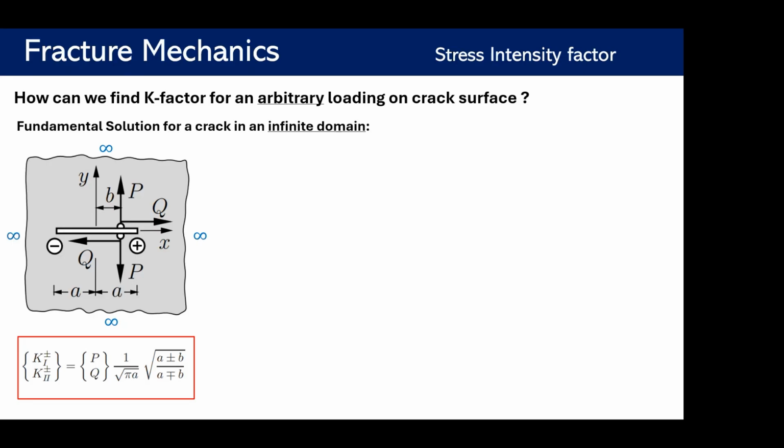So a fracture in an infinite domain. And we have applied two concentrated forces because the problem should be in an equilibrium state. So we have two concentrated forces, P, at a distance of B. You can see the B and the B. So P is a concentrated force at the fracture faces at a distance of B to the origin.